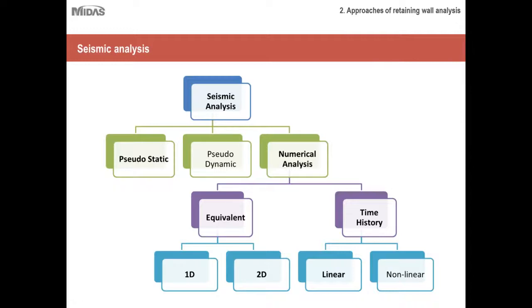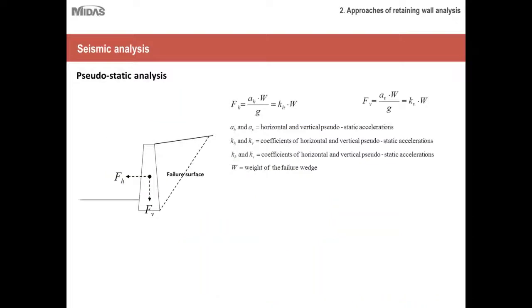The reason I've done this is that pseudo-dynamic and non-linear time history analysis are rarely used. I haven't seen any engineer applying pseudo-dynamic analysis. I have seen cases where non-linear time history analysis is needed in very high seismic zones, but pseudo-dynamic analysis is hardly used.